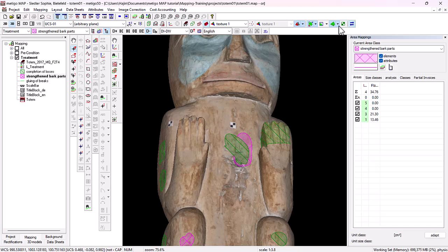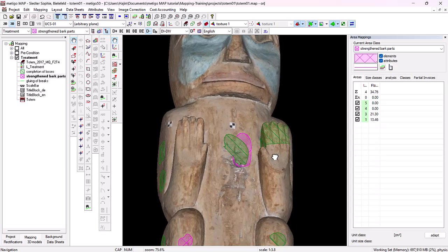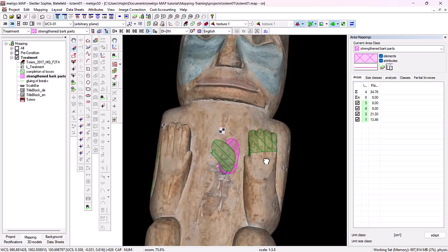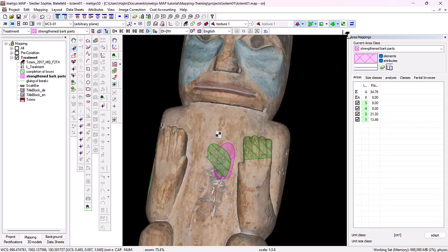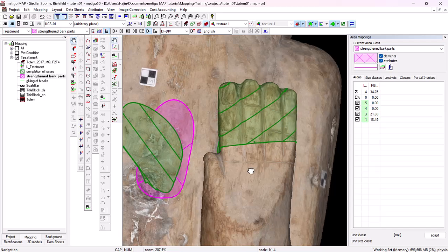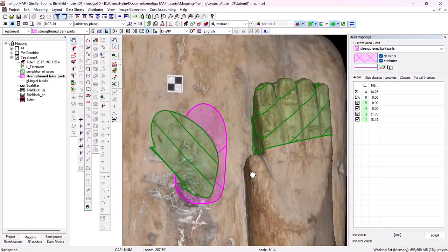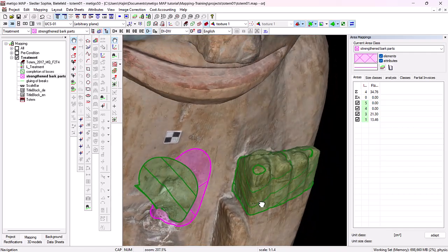We have three settings here. I can project the hatching on an image plane, and then the display is parallel to the currently selected display projection. I can align them firmly in the image plane, or I can align them to the element. Then the hatching doesn't seem to move, but then I have these kind of effects with the hatching that goes around corners.